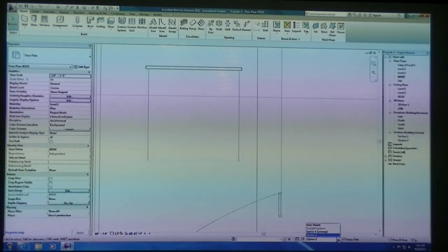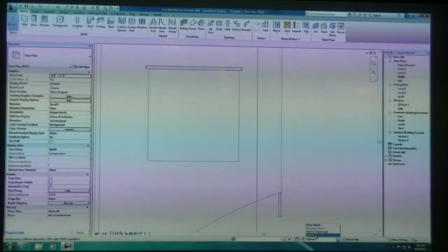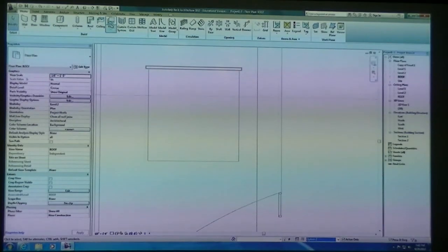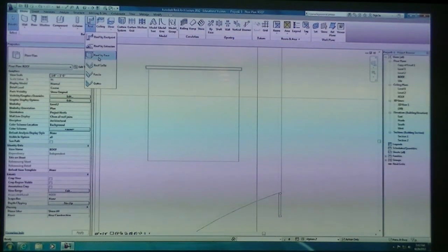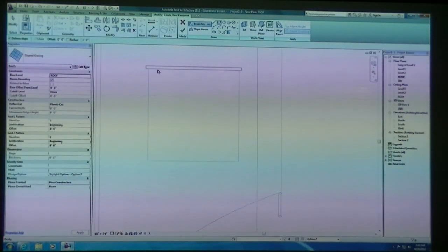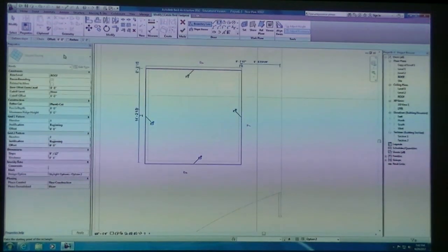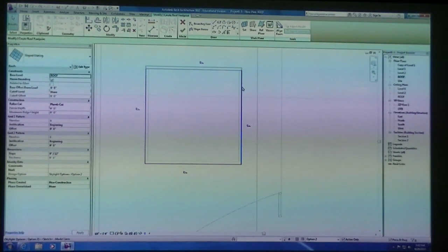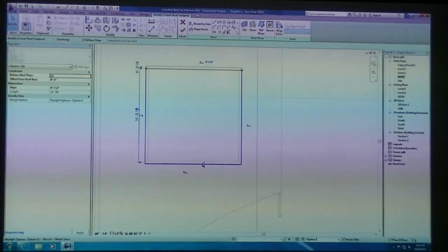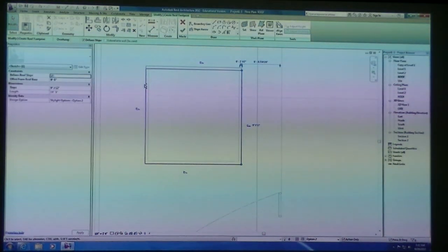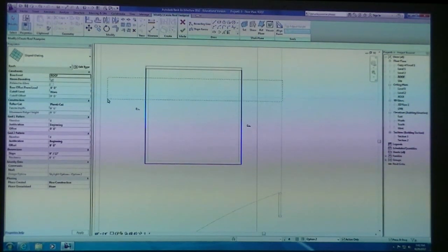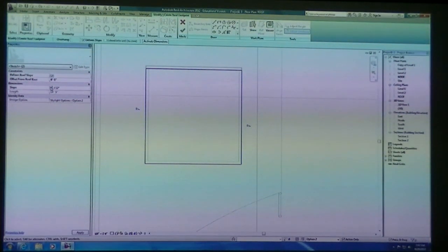So down here at the bottom, you can toggle if you're in the main model, if you're in option 1 or option 2. And then I can start modeling. You can see everything grayed out while I was in option 2. And I can come in here and do my sloped glazing. So roof by footprint. I'll do sloped glazing. And this time I'm going to make it a gable and not a pyramid, just for this particular one. Make those something drastic like a 1412.